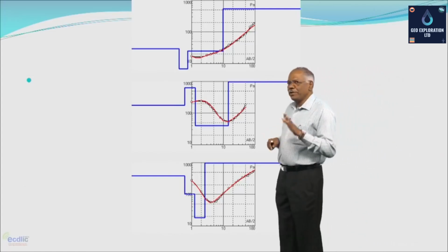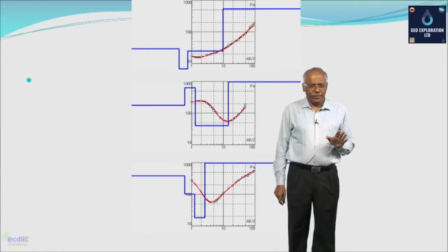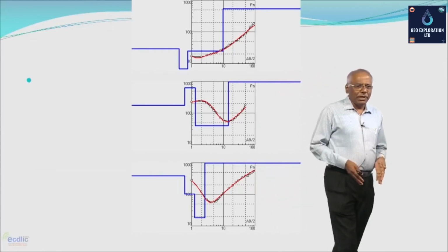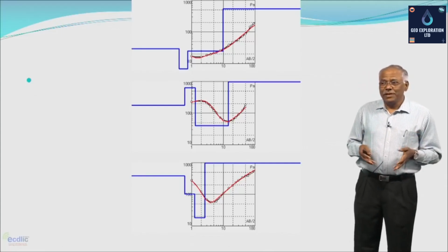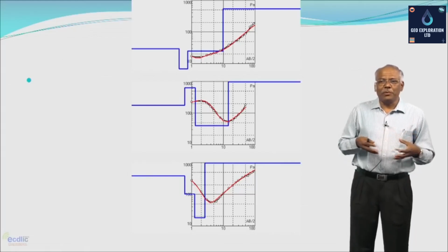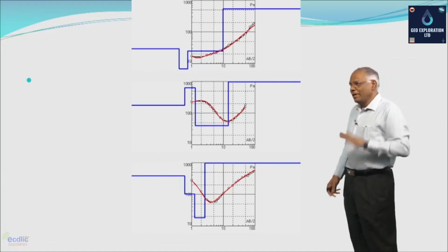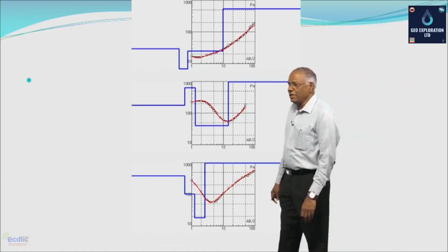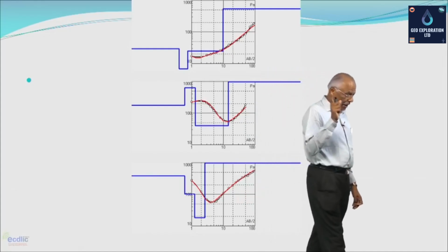A type of curve is typically devoid of occurrence of groundwater, because as you go deeper, electrical resistivity is increasing, and when the electrical resistivity is increasing, there is no resistivity low which will indicate saturation of a rock formation with water. That means it is devoid of any porosity and permeability, and therefore devoid of any water in it, and that is typically an A type of curve.